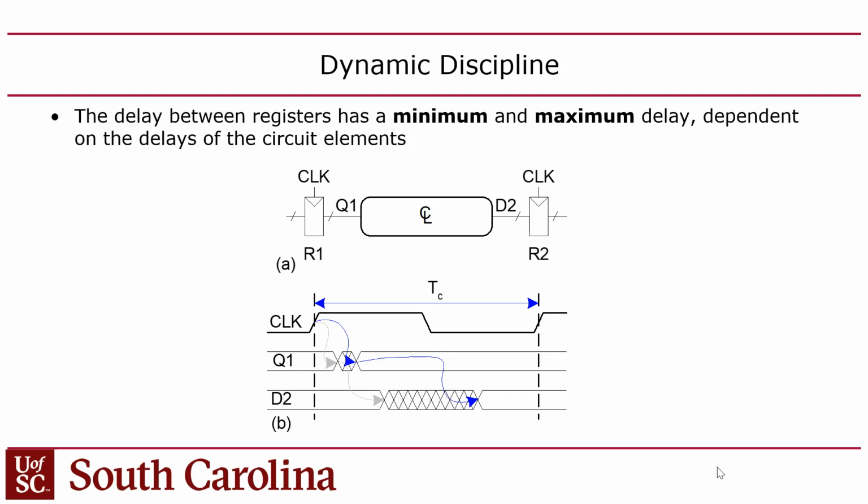Now the power consumption of the chip is proportional to the voltage squared, right? So by changing the voltage, you get a huge benefit in terms of power consumption. But when you do that, you have to clock it down as well. Did you have a question? Yeah, when you say change the voltage, do you mean supply voltage? Supply voltage, right. Yeah.